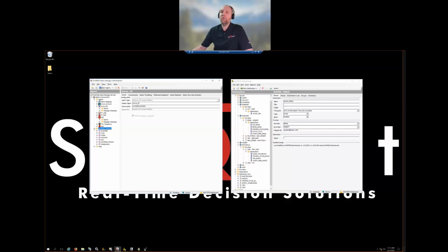But I'm going to first show you what an escalation scheme is. This is our templatization of who gets messages and when. I've got an OPC escalation scheme here that has multiple different levels, meaning multiple ways of escalating that. And then I've got a system platform escalation scheme that really just has one level. And ultimately, we're going to send a couple of messages with a gap of 300 seconds or 5 minutes in between. And so a customer gets to dictate exactly how many escalation schemes they want to create, how many levels within that. It's entirely customizable.